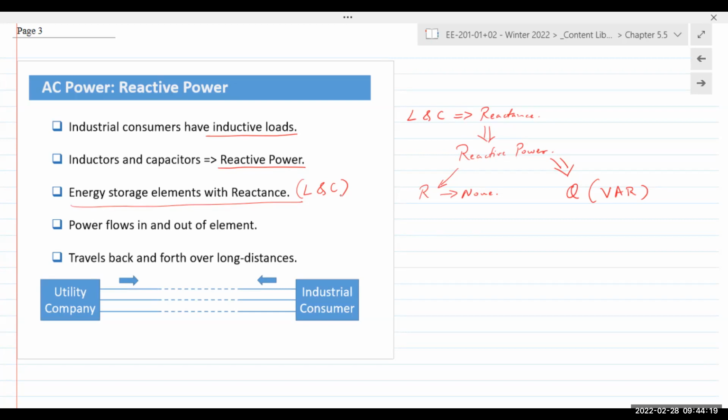But unlike an industrial customer, residential customers are not going to run washer dryers 24/7. At most, you might run it once a week. Now, again, if it's a coin laundry or something, they might have something going on at least 20 hours a day. But still, compared to an industrial customer, that kind of load is insignificant. It's nothing, essentially. So it does not really matter to a utility company if residential customers are using small appliances or large appliances. Those inductive loads do not present as much of a load.